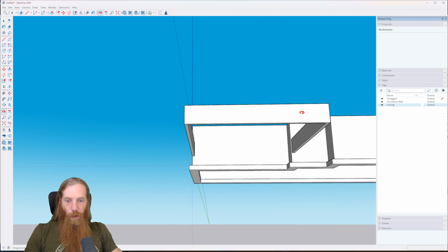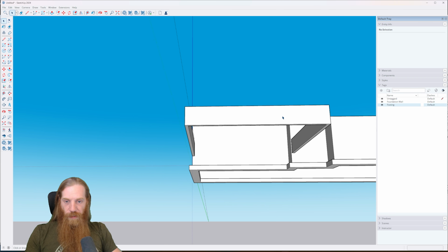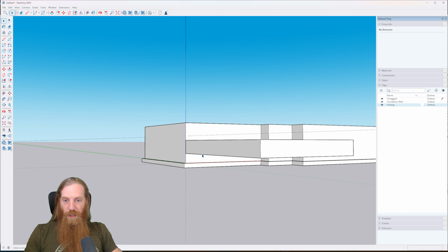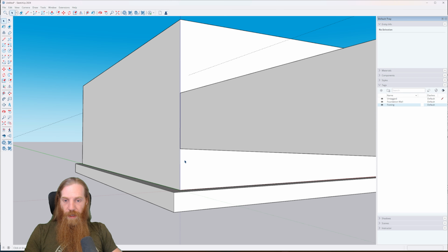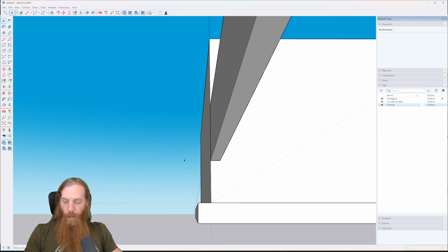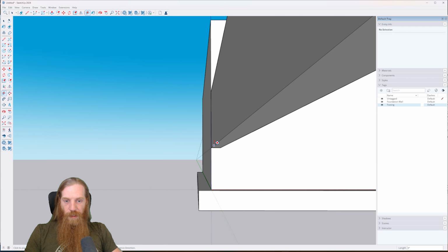We just need to do our footing for the garage, right? Obviously the garage stem wall needs a footing as well. This footing is not going to be as deep because we don't need as much wall. It's not going to be as deep as the house footing was. But again, it's going to be a 24-inch wide footing, so we need to come out 8 inches on both sides. So I'm just going to do reference lines, 8 inches.